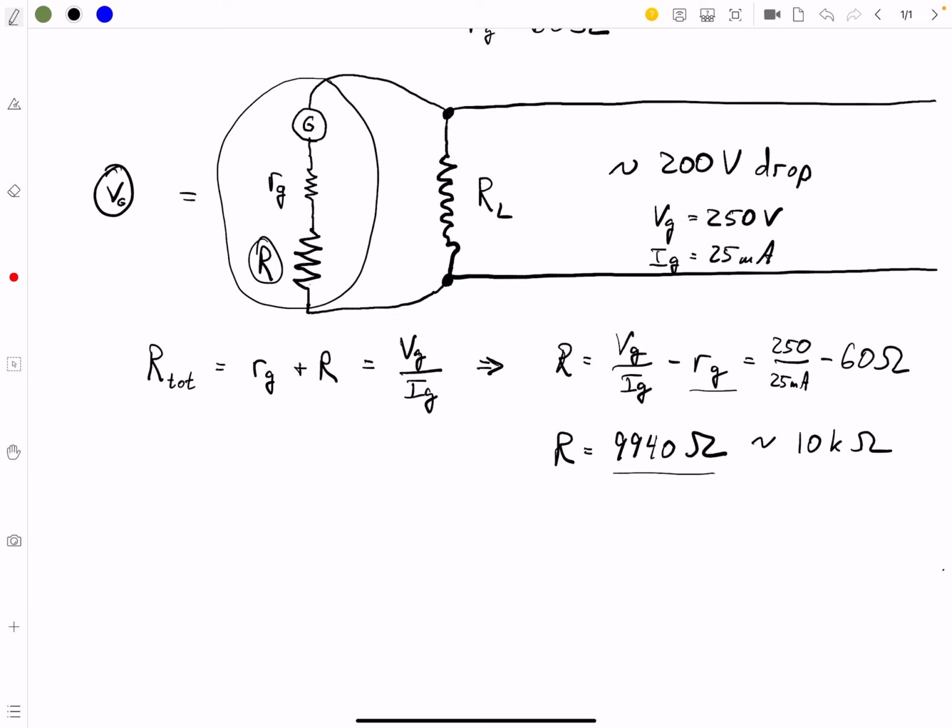It's going to have a top side that has the internal galvanometer resistance. It's going to have the actual dial itself, and then it's going to come down. And then over here, it's going to have another resistor that is called a shunt resistor. RS is equal to a shunt resistor.